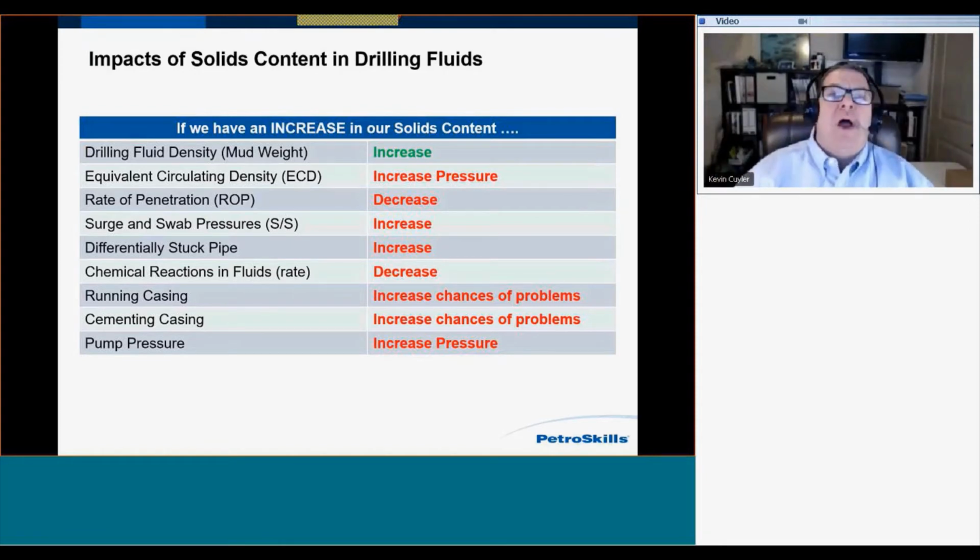And that is why whenever we land our casing, we always want to circulate the wellbore clean, get all the solids out. If we've knocked some off the formation as we went down into the wellbore, anything that was left that we didn't get out the first time, we want to circulate those out and get them out of the mud as quickly as possible, preferably at the shale shaker at the first available opportunity, so that we get a good cement job and we can continue drilling on, or if it's production pipe, be able to produce the well.